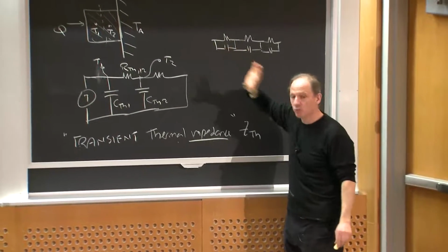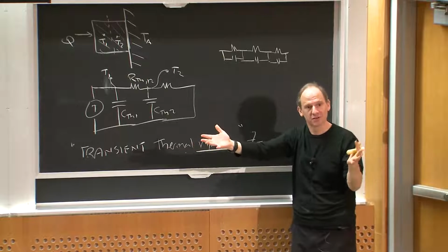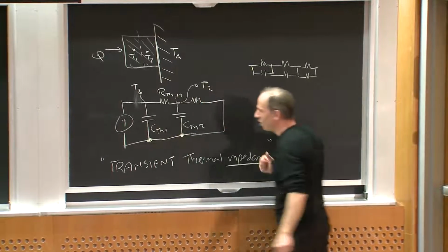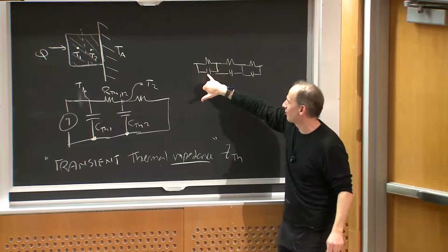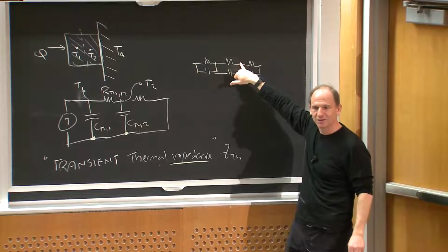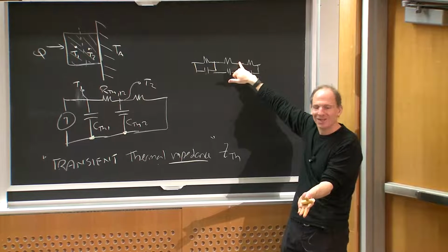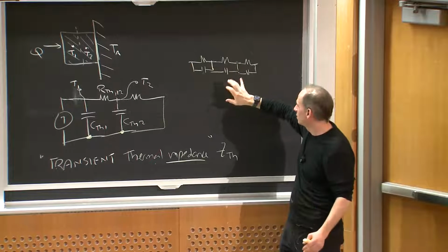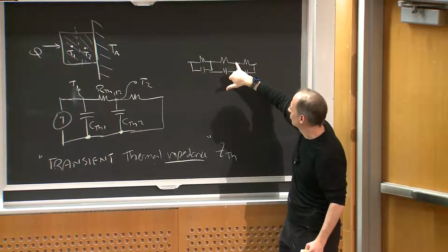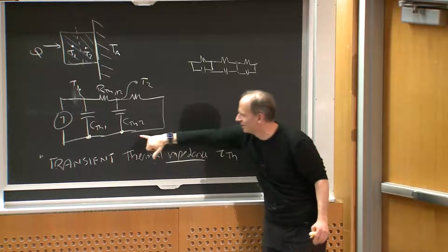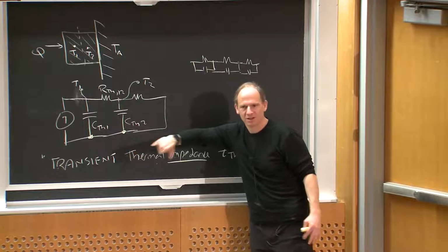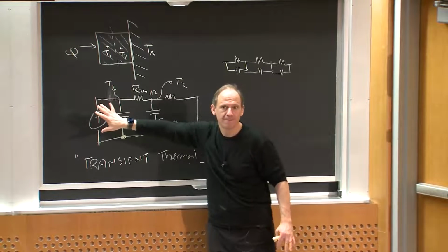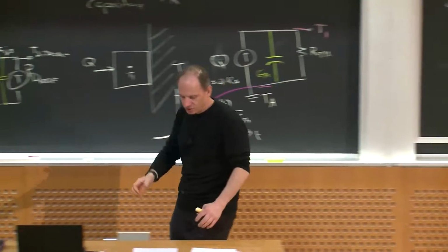You can kind of try to take this kind of model and map it over to that kind of model, but any real thermal capacitance, if you're going to represent Fourier heat transfer, thermal capacitances ought to always be down to, we can use ambient, but it should always technically be absolute zero. These are referencing the thermal capacitance to other places in the thermal path where the temperature is changing, all right? So it's basically just not right, but people do it because it's convenient. And I suppose, if the thermal capacitance here or the thermal resistance here was super low, maybe it's almost like this was at Earth, so they can kind of get away with it sometimes. But it's just a warning. If you want to stick with the physics, this is the correct kind of model to use. Okay. So that's just giving you a heads up.